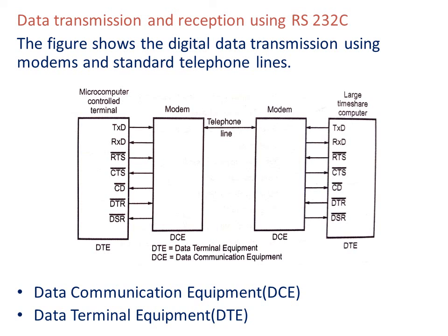When the modem connected to the sending terminal receives this carrier, it asserts the carrier detect, CD bar signal, to the terminal. After a proper time interval, the modem sends the clear to send signal, CTS bar, indicating the modem and communication channels are ready for transmission.